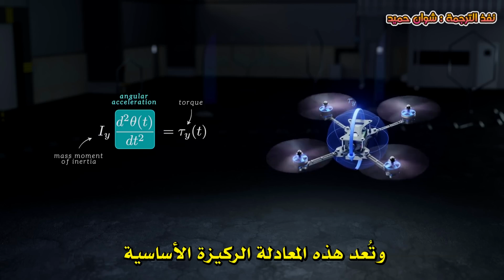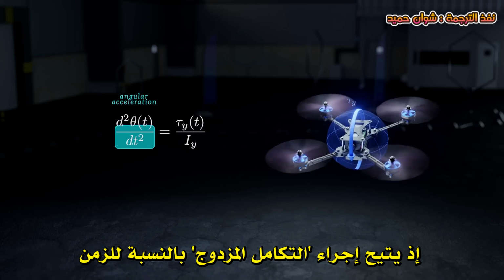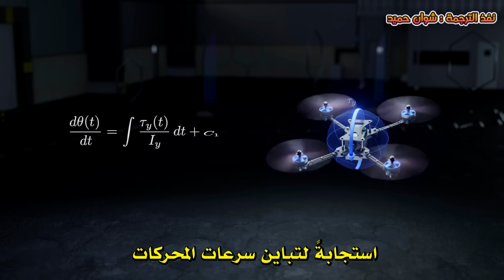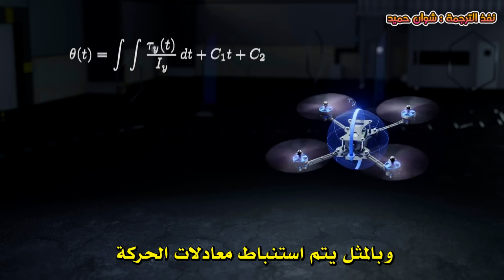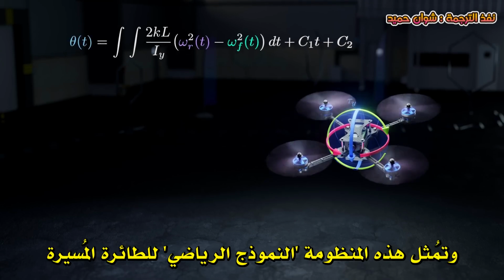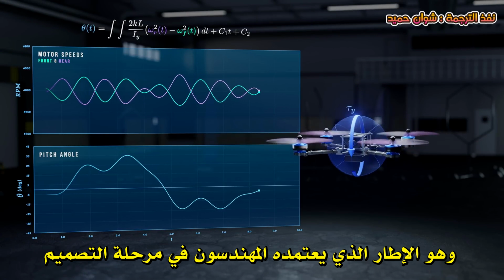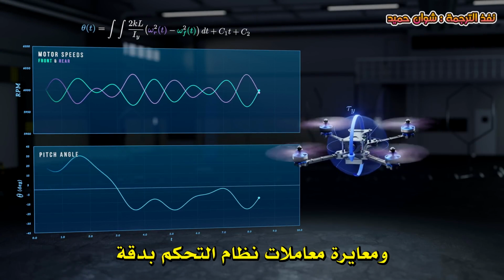This equation provides the foundation for simulating the drone's motion. By integrating it twice with respect to time, we can calculate how the pitch angle changes as the motor speeds, and so the torque, are adjusted. Similar equations can be derived for the roll and yaw axes as well. These equations form part of the mathematical model of the drone, a model engineers use during the design phase to simulate its behavior and fine-tune the control system parameters.